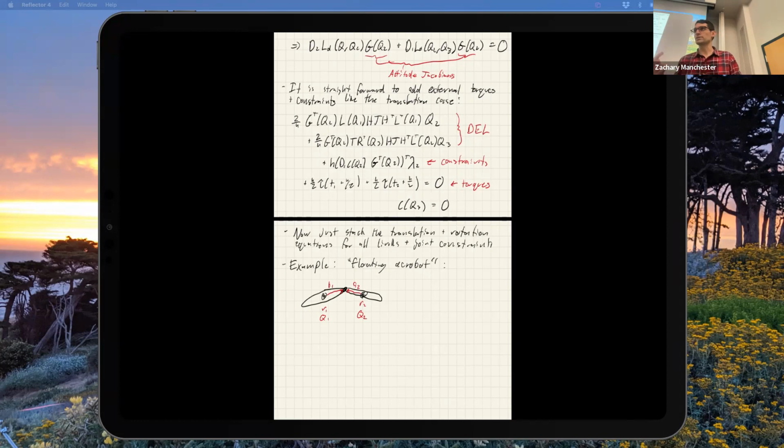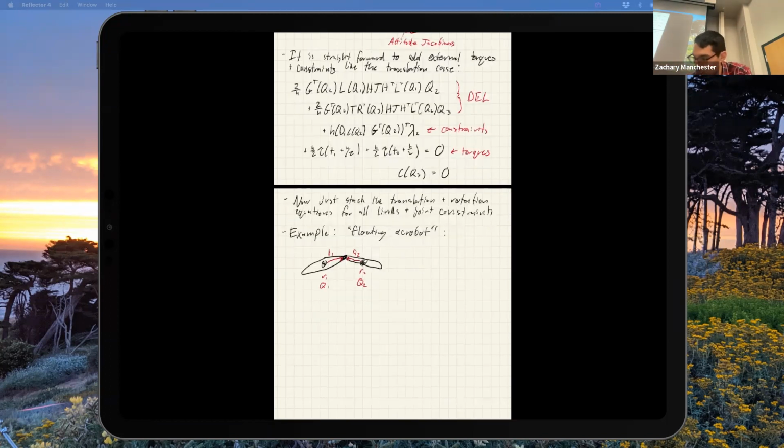There are two pieces. There's the position piece that says these two points have to lie in the same inertial position. And then there's an attitude constraint as well, because I'm going to make this a revolute joint that can only rotate about one axis. We're in 3D, so I have to constrain away bending in this direction and twisting in this direction. So those are the two things I have to do. Let's write down the position one first.